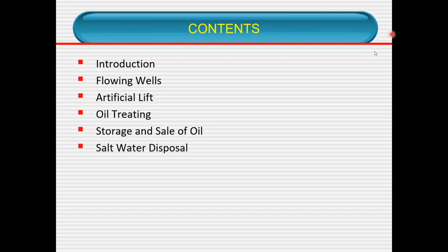If it is wax, whether it is at the upstream or at downstream, it is going to work, because the chemical was not developed because it is upstream or downstream, but because it is wax, or even inorganic scale, calcium carbonate or barium sulfate. So it should work. But the only difference, I would say, is the application part of it.